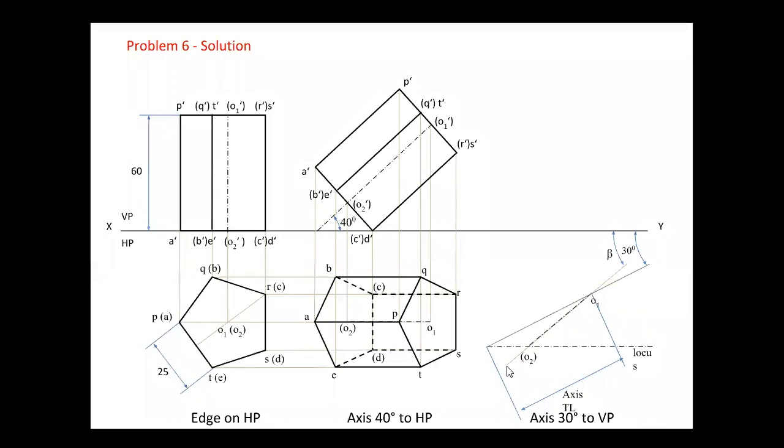So this is my point A here. A to 2, I'm drawing a 90-degree line in this case. A to 2, A to 3, and the same distance from point A to 1 and A to 4. Join the rectangle, then place all the required points on that rectangle.